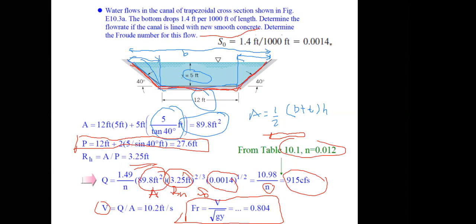So from looking at the slope and the depth, we can estimate the flow rate and the velocity of the flow. So these are pretty useful equations. If we have the information on the geometry of the channel, then we can derive the velocity or the flow rate.